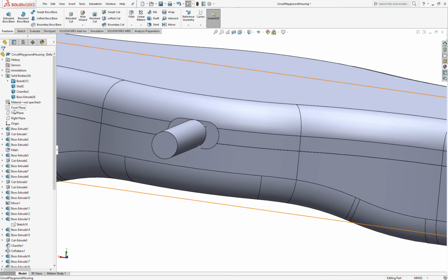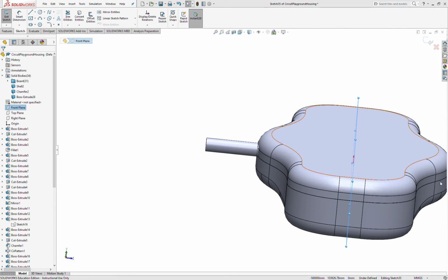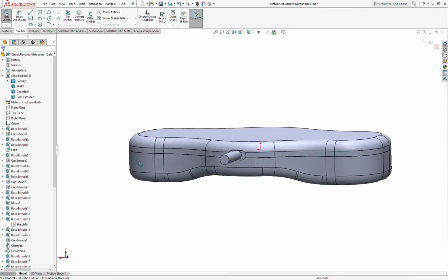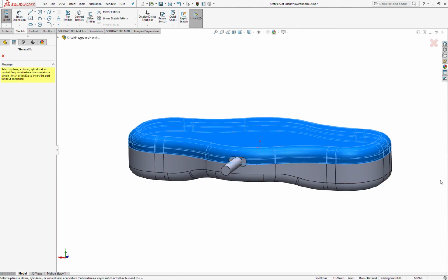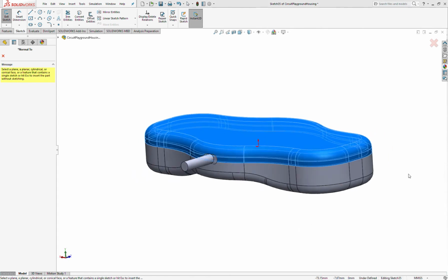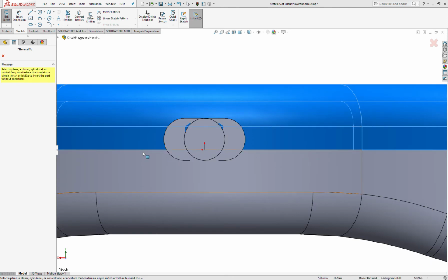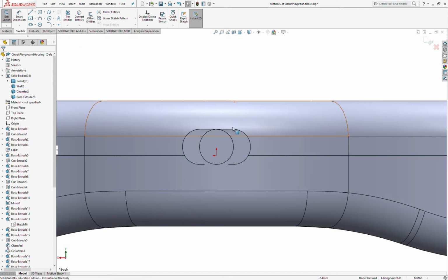We're going to sketch on the front plane. There. And we want to be on the side of our cord. So if that's our split line, right? Whoops, other side. If that's our split line there, we want this portion of the upper to actually be part of the lower, and then we'll take a hole out of it. So pretty straightforward in order to do that.